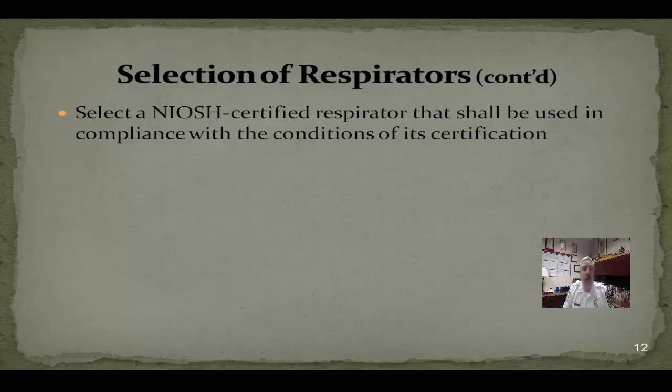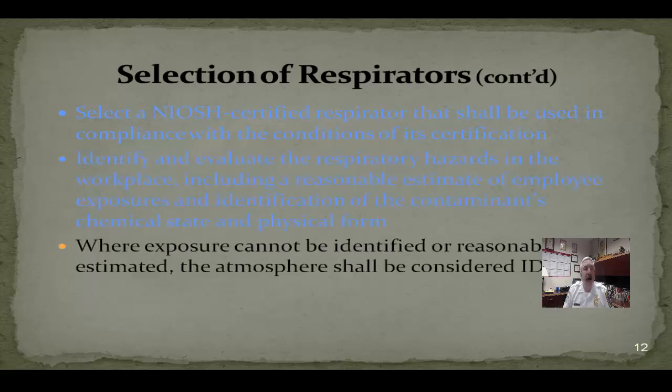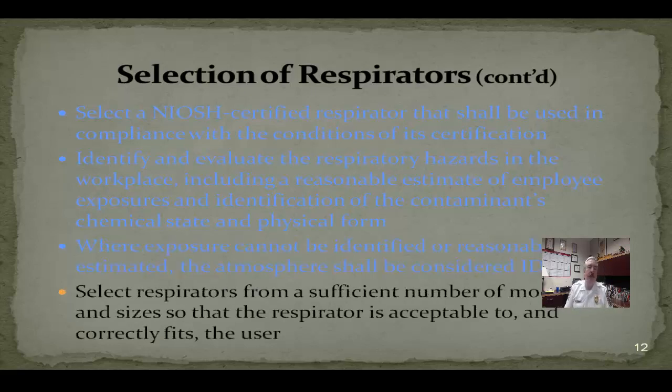Those respirators, those filter materials, need to be certified for the jobs that they're doing. You need to make sure that you're using the right filter for the environment in which you're in. And any time that you can't identify what the environment is, you should automatically assume that it's immediately dangerous to life and health.